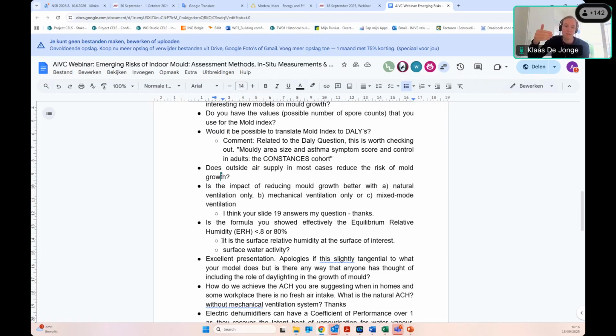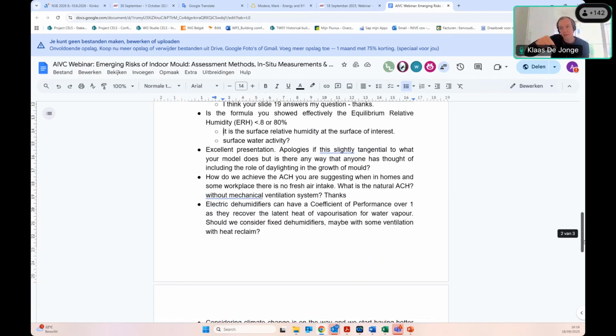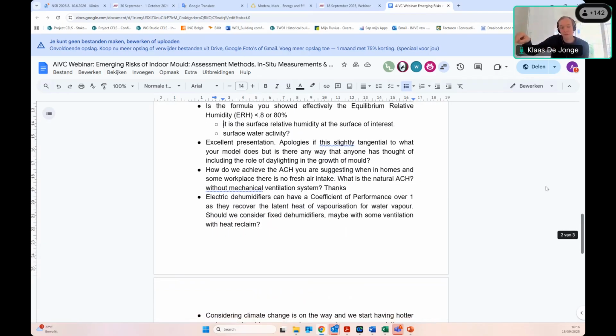And then in the top layer, at the first micrometers, let's say, you get a good estimate of the relative humidity levels in the material, and that went as input to the Finnish mold growth model together with the surface temperature of that layer.